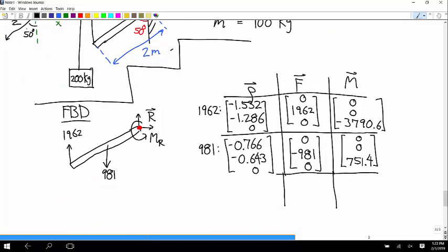And now we're down to that reaction force. This is in a plane, so there's only x and y components for r. Well, this is the reason that we chose the about point here. What's the row vector for that force R? 0, because they're at the same place. The force vector is Rx, Ry, 0. And so the moment is 0, 0, 0.